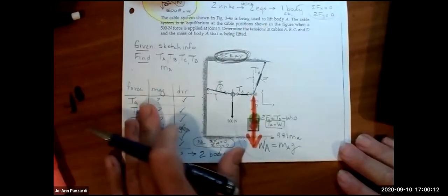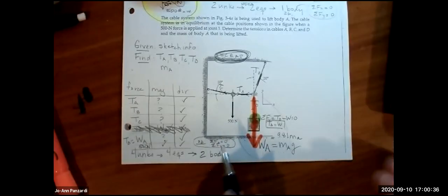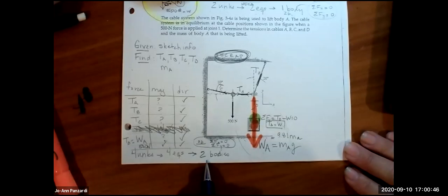Okay? Jason, did you have a question? Maybe I don't get the 2D sum of force X, sum of force Y thing. Okay, so for every free body diagram we draw, we could sum the forces in the X, and we could sum the forces in the Y, right? From physics. So that means from every 2D body, every free body diagram I draw, I could get 2 equations. So the fact that I need 4 equations means I need to draw 2 free body diagrams.